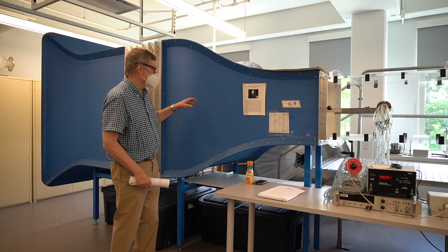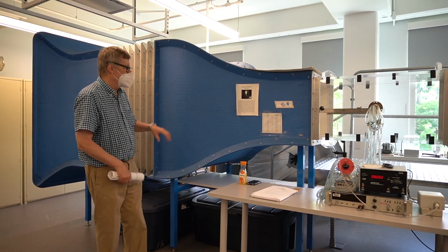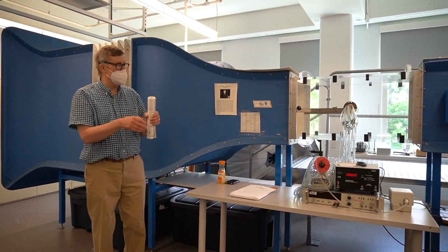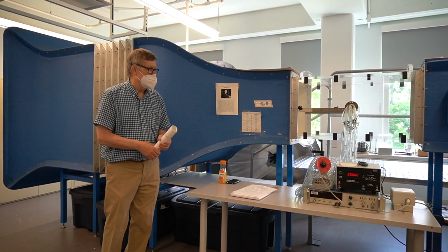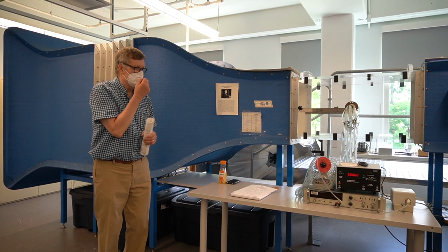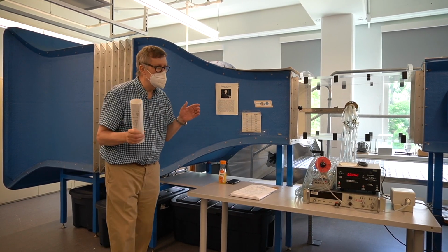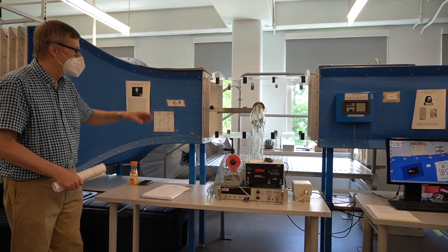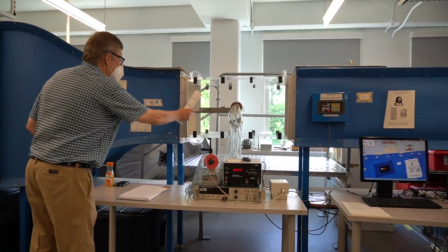And so, according to the conservation of mass, the flow speed here is slow, and it's very fast there. Where you make the flow go through a little hole, it goes faster. And so you end up with extremely good, uniform, low turbulence, high-speed flow in this test section made of lucite. That's this thing.